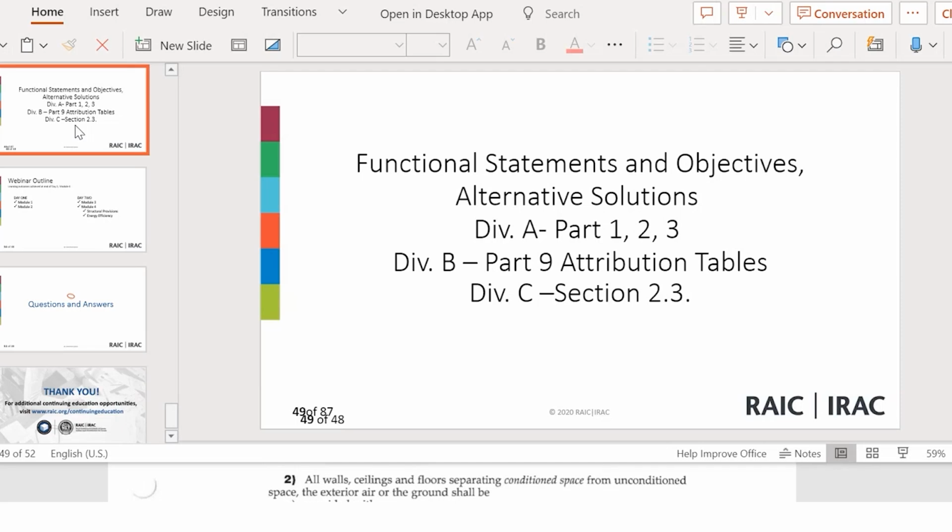They will take care of the compliance of the electrical and mechanical systems. For energy efficiency, for residential and Part 9 buildings, you need to decide what approach you want to use for compliance. And for plumbing fixtures, you've got the options: certainly you use the requirements of Part 9 and 3.7 for occupancies other than dwellings.